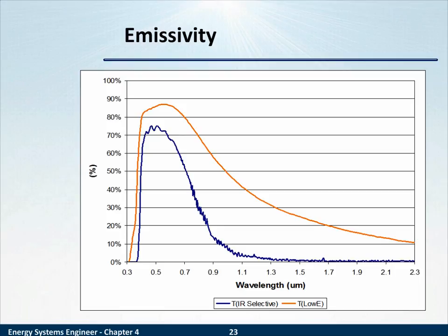This is why, if you live in a warm climate, as I do in Phoenix, this is why even though you have, quote, low E windows, you still have too much heat coming through the windows, because low E blocks a different type, a different wavelength of infrared versus an infrared selective glass or film.